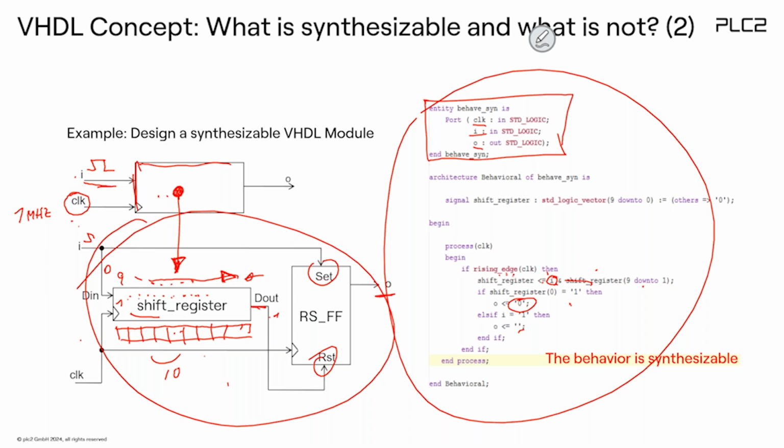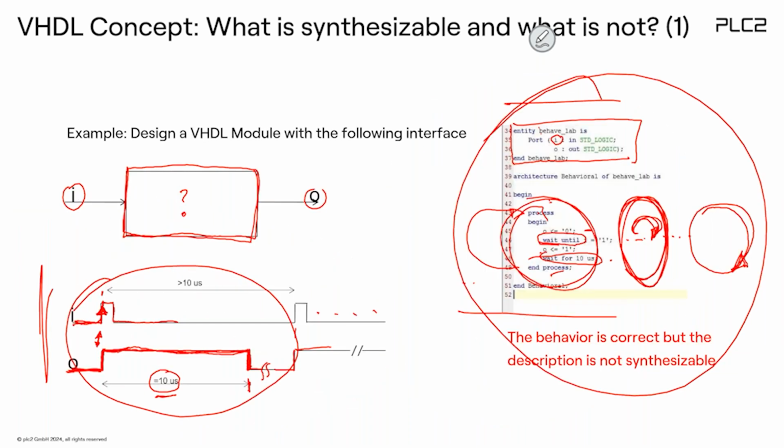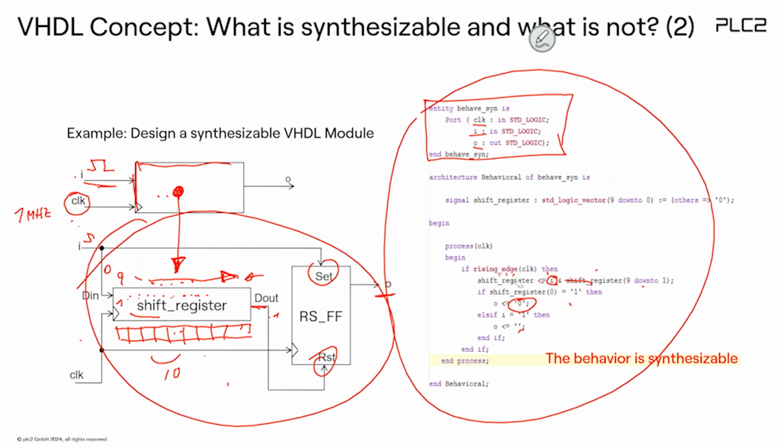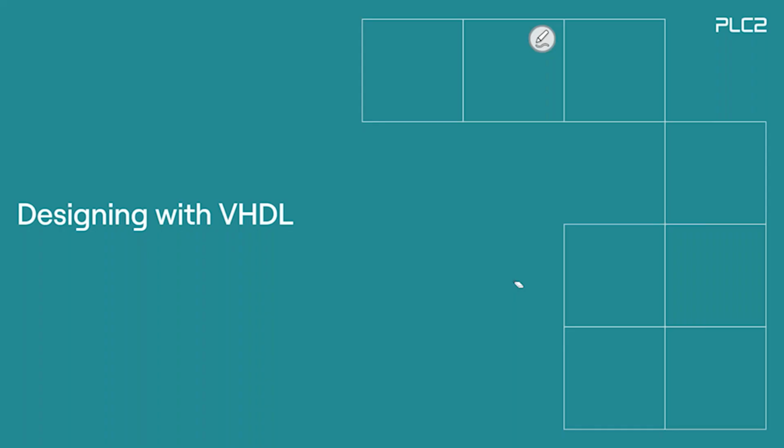This means that the structure and behavior you describe for simulation is usually very simple. You can use statements like wait, wait down a little bit, and maybe wait until this. But if you need to synthesize, you have to understand the real function, because now we really need to describe the function which is synthesizable. So in this case, we have to deal with adder, counter, flip-flops, RAMs, and so on. So you need some kind of understanding of the real hardware.